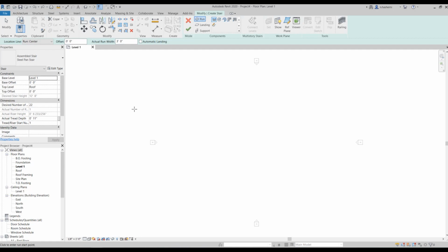If you want to draw a stair, you just need to select one of these types. And as you can see here, the run is selected by default, so you just need to click and it's all done. Okay? Or you can use just one of these shapes to create a stair. For example, I'm going to use this one and then just draw a stair.